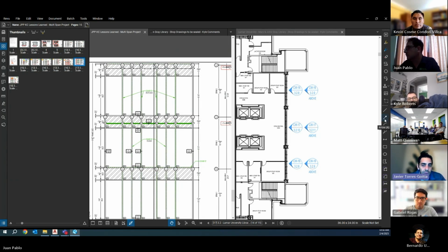We originally wanted to get everything to work by applying the full perpendicular load, in the direction normal to the frame, in addition to a parallel wind load event that would simultaneously load the cover. We quickly ran into problems, and the weak axis capacity for stress and deflection was really a limiting factor.